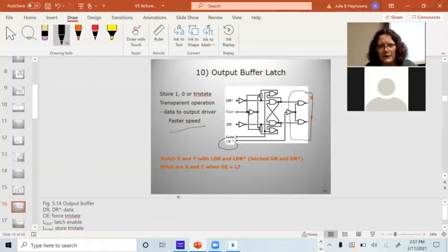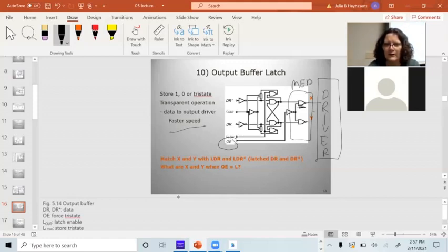Well, not yet. We're not driving the capacitance yet, but we're going to start scaling the size of the transistors up, because remember, the latch has to power the driver. The driver is what's driving the 50 to 100 picofarads. If I made the latch minimum size logic, it wouldn't be capable of driving the driver. So you step it up in stages. This is going to be more medium sized, and the original drive circuitry will probably be small drives.